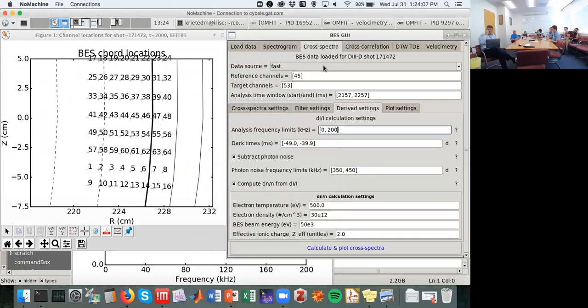You can go into the GUI and type in all the channels down the line: 41, 42, 43, 44, 45, 46, 47, 48. And a nice shortcut trick, if you don't want to type in every channel number, is you can use basic Python functions like range. So for this one, I'll just type in range(49, 57), and this will automatically generate a list going from 49 to 56. So it's a shortcut versus typing in everything.